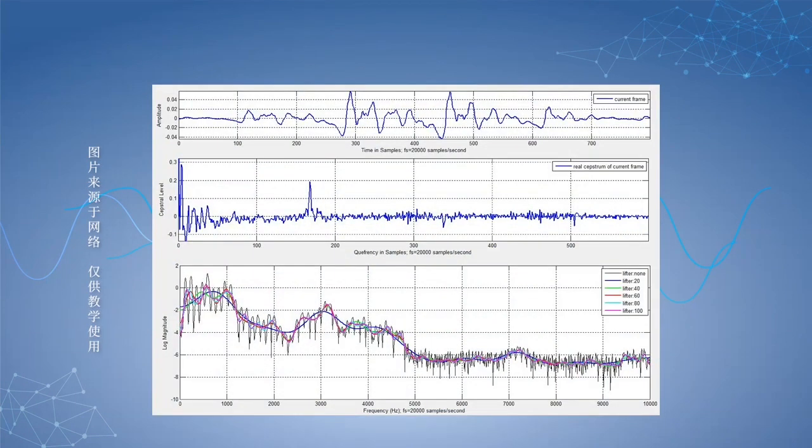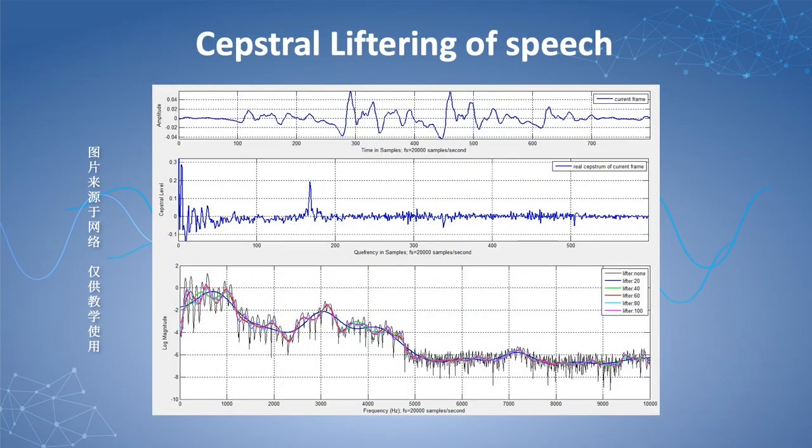This figure shows the spectral smoothing effects of low-frequency spectral filtering on the log magnitude spectrum of a speech signal. This is done by first computing the real spectrum of a window-weighted frame of speech and saving the resulting log magnitude spectrum as the baseline unsmoothed speech spectrum.